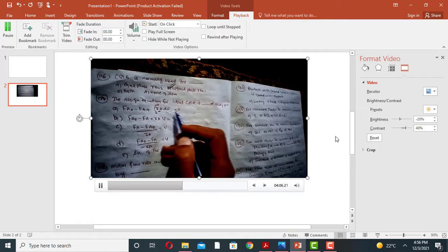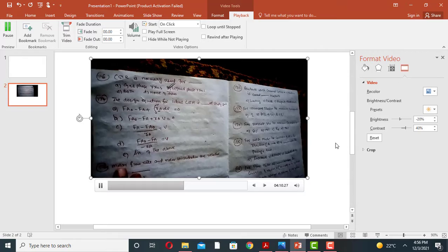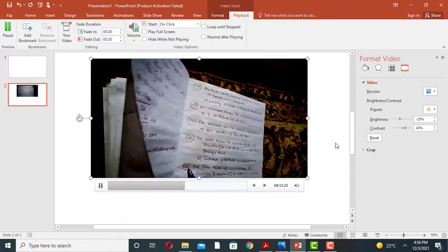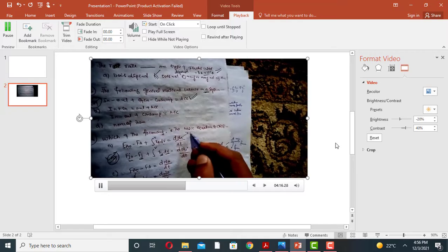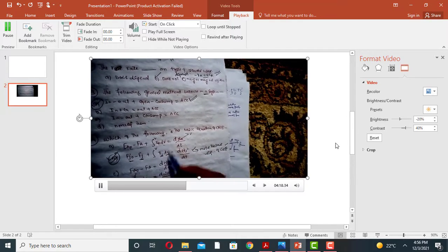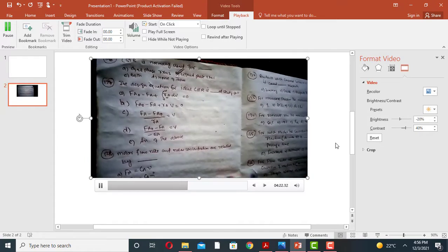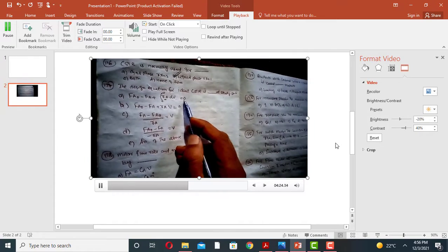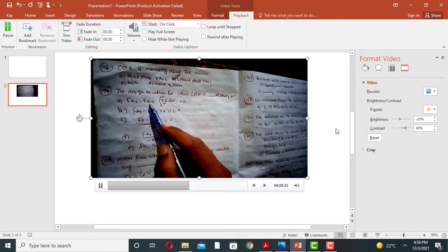The design equation for the ideal CSTR at steady state is input minus output plus rA dV is equal to dNA by dt. At steady state, the change in moles of A with the passage of time will be 0. So at steady state the accumulation term is 0, and we can rearrange this.